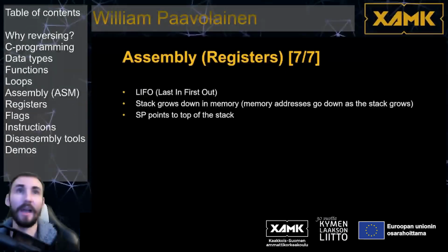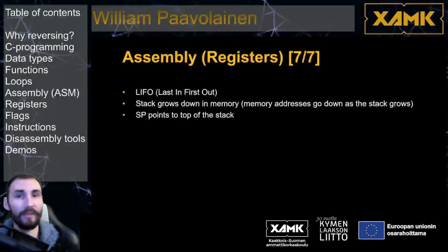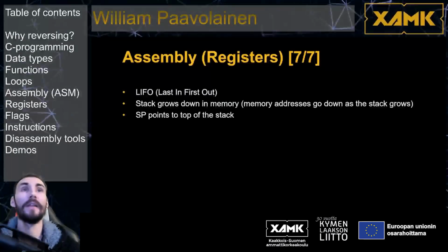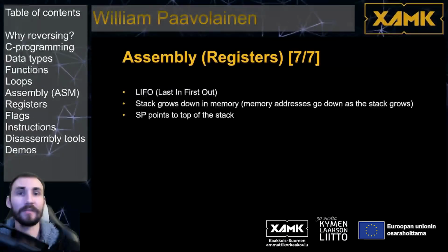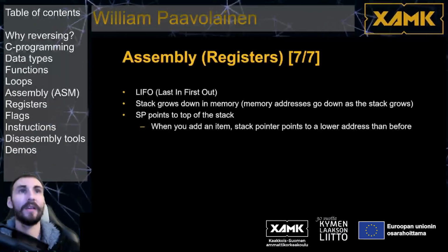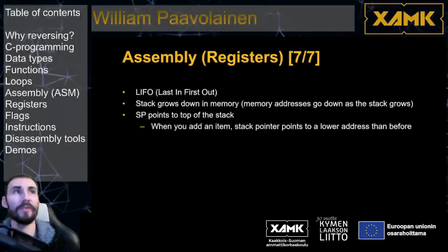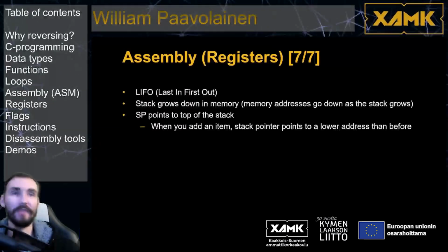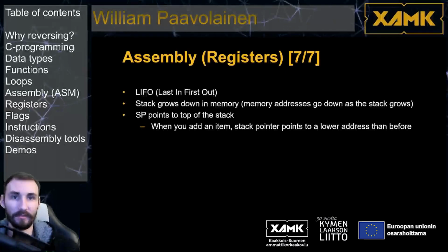But yeah, then we have SP, which is the stack pointer, if you remember. And it always points to the top of the stack. So the last item on the stack, the stack pointer will point to that one. And when you add an item, the stack pointer points to a lower address than before, because the stack grows downwards.